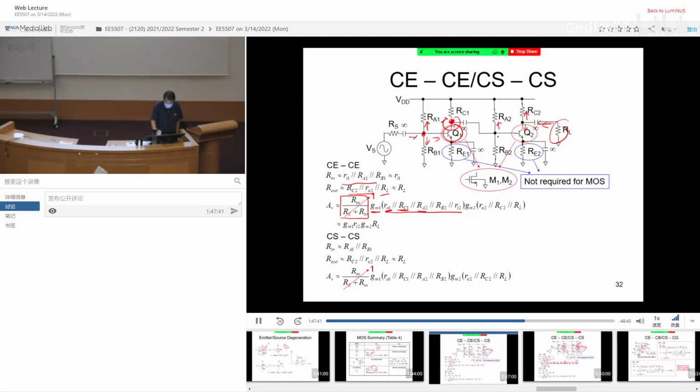You look to the right bottom, you see RB2. And you look further to the right, you see RI2. So basically, at this point, the current source, what are all the resistors, the total resistance connected at that point. So once you get this point, you just turn yourself around 360 degrees and you figure out all the resistors connected to this point. That is how you do it.